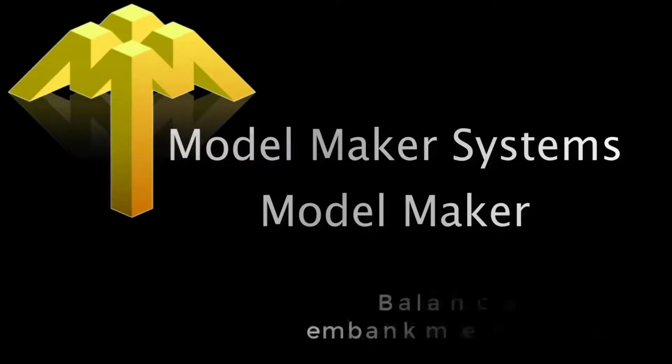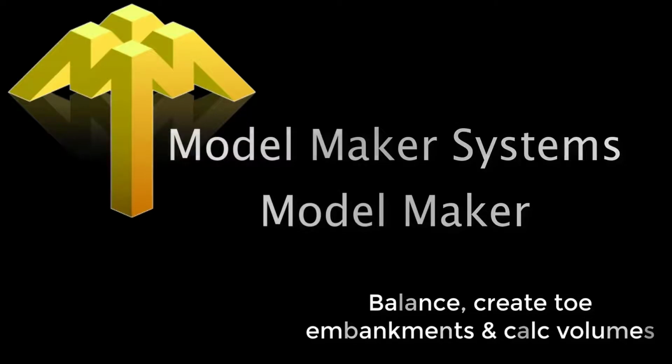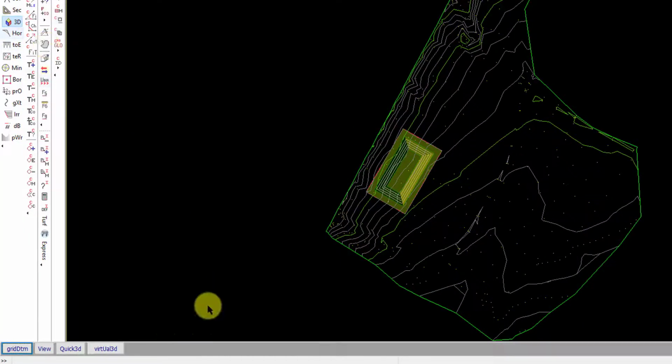In this tutorial I will show you how I will take a basic design that I've already done for a dam basin or a storage reservoir. I will balance the cut and fill and calculate toe lines, and then calculate the final cut and fill volumes showing the balanced quantities.